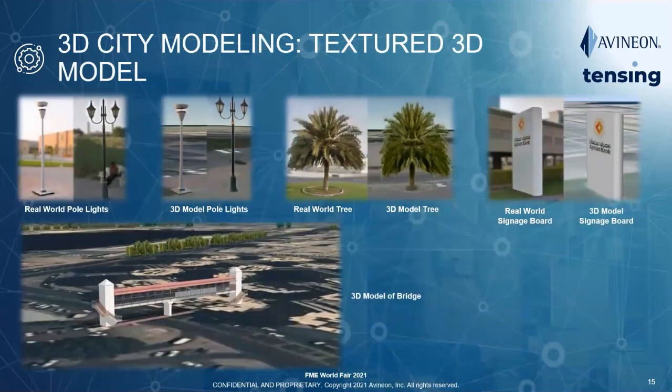And then we did all the texturing and all these different images of poles and trees and bridges based on the NC Tech Pulsar system. The sensor resolution here was 60.5 megapixels, and it would capture images in a 360-degree manner from 4 fisheye lenses. So these high-resolution images provided photorealistic textures to the buildings.